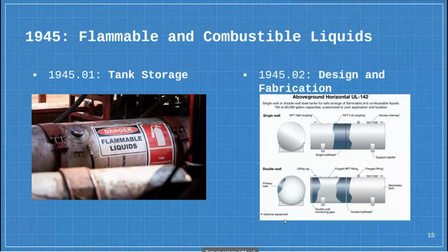So, yung design nito, dapat approve siya sa API or yung American Petroleum Institute. May standard siya sa paggawa ng welded steel storage tanks para sa mga oil or other liquids. And meron din part dito yung ASME, so American Society of Mechanical Engineers. Dapat pasok sa safety nila sa mga standards para masigurado natin na safe yung tanks natin. So, ayun. Dapat approve din siya yung supervise ng bureau. So, next.